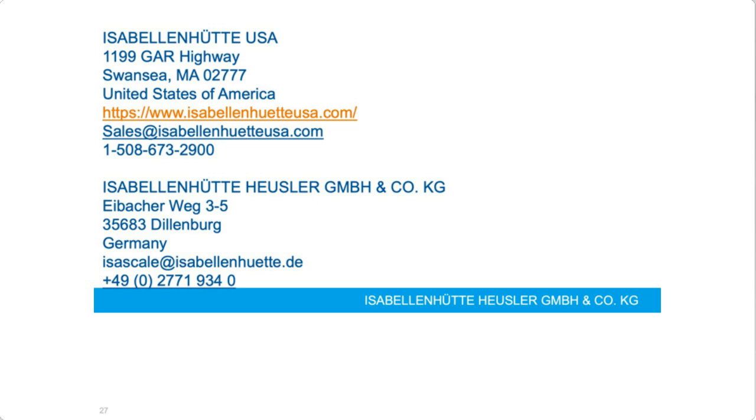Yes, that's a very good question too. Thank you for that. First of all, yes, with active isolation monitoring, you can monitor a non-energized bus. However, you don't necessarily get a valid reading for every possible combination of contactor states.